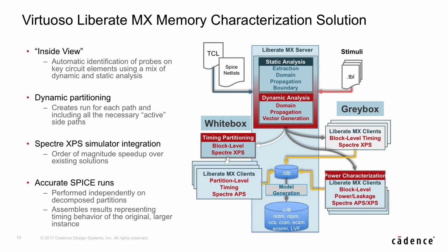We use dynamic partitioning to carve out the netlist for each critical path, so that you can use a more accurate SPICE simulator to run on that netlist.